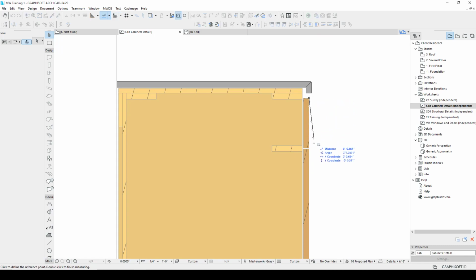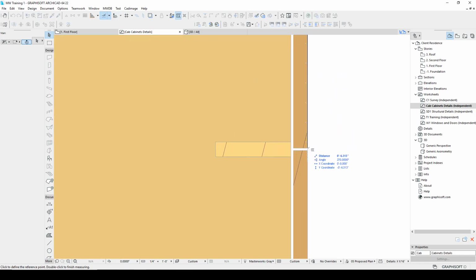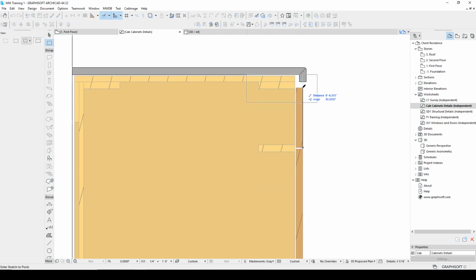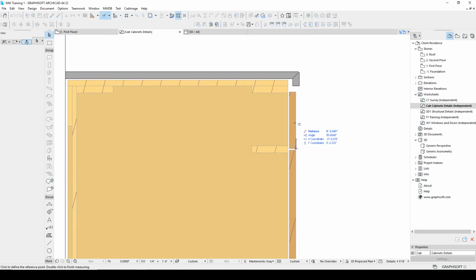And then I want this front. So this front is not 6 inches. So maybe that was one of our design goals. We wanted this to be exactly 6 inches. So then we can marquee this, click this point, move our origin to this, and make this 6 inches exactly. And now we have a 6-inch front, which could be the minimum if you were not using a slab door, but a 5-piece front, you needed a 6-inch from the manufacturer.